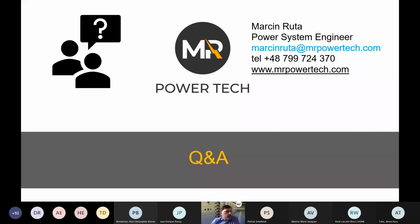What is the best solution in case of fire for substation rooms? Automatic extinguishers like FM200 or CO2. In case of fire, yes, that's what you wrote. CO2 maybe not, because as far as I know, it's forbidden in some countries because it causes deaths. It throws out the air from the substation, so if you are inside, it's dangerous to you.